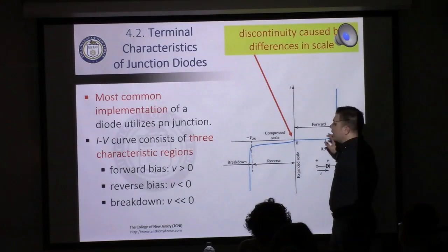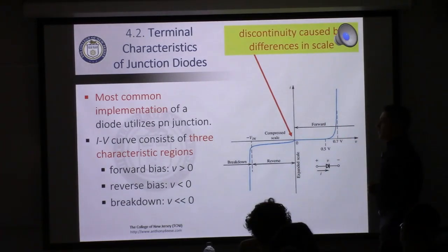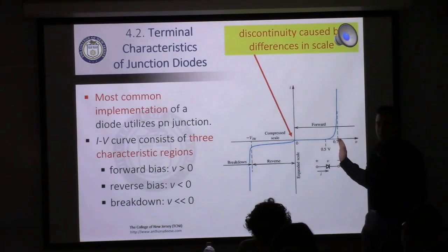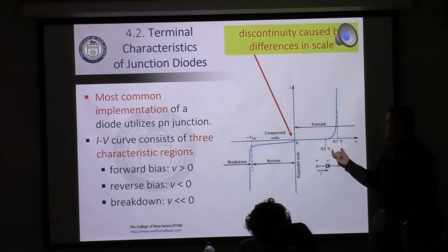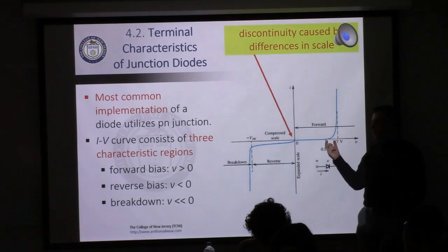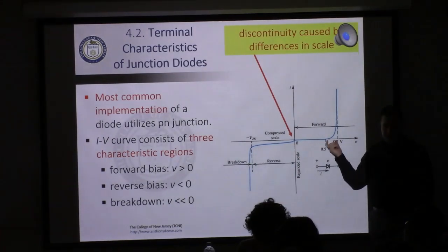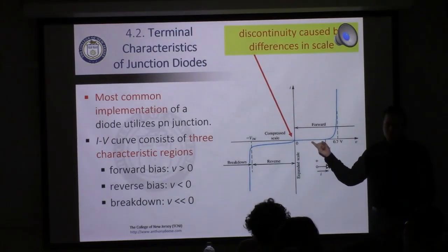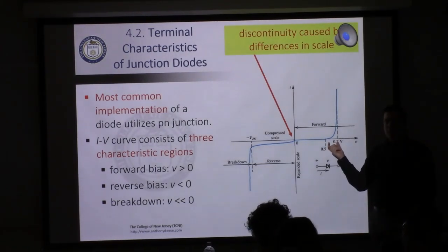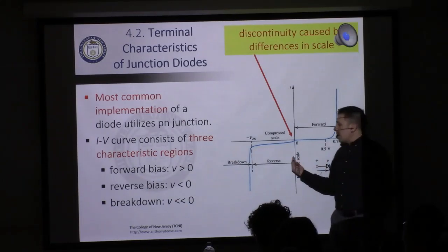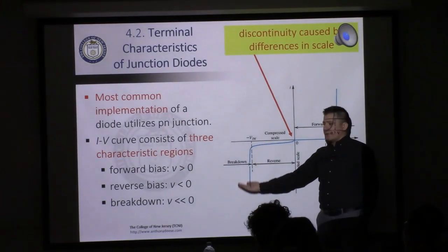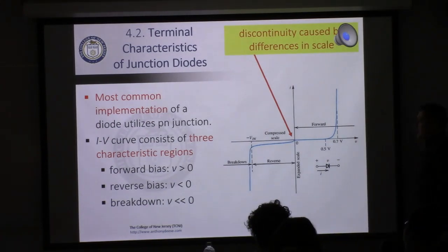So we really have 3 or 4 different regions that we have to look at when it comes to the diode. Obviously, we have the forward biased region. This can kind of be split up into the forward biased region, which we also call the conducting region, and what we call fully conducting, right? Because in this part, we're conducting, but you would not consider this to be a short circuit right here. This is not very much current flow. Over here, this is what we call the fully conducting region. Then obviously you have your blocking reverse bias, and then you have your breakdown reverse bias. And that's for when V is much, much less than 0.